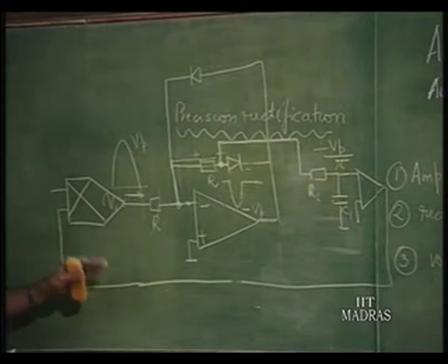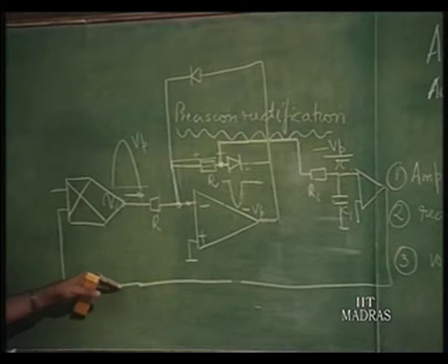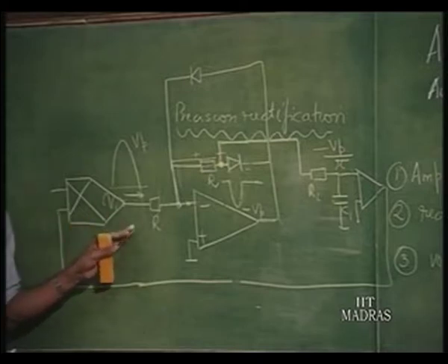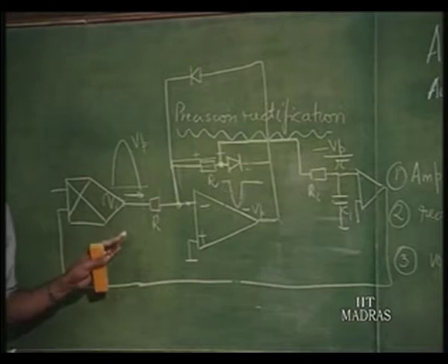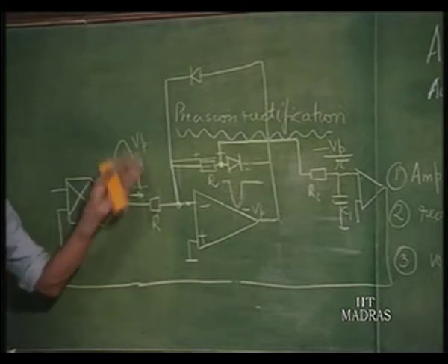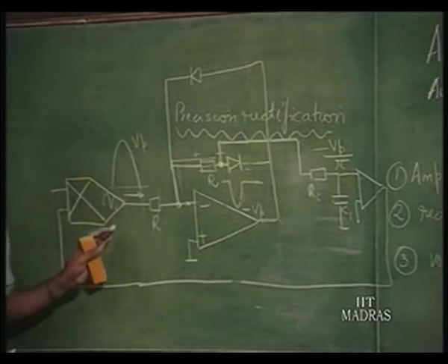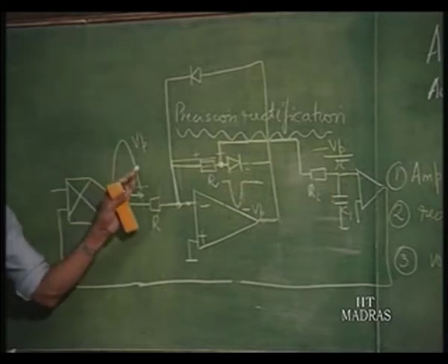Now, again here the voltage can be negative or positive. For both negative as well as positive, this will work as a voltage controlled amplifier, but in one case there is a phase shift of 180 degrees, in another case there is no phase shift, that is the only difference. As far as the phase shift is concerned, for amplitude it does not matter at all. So, the phase shift of this is of no consequence for the amplitude here.